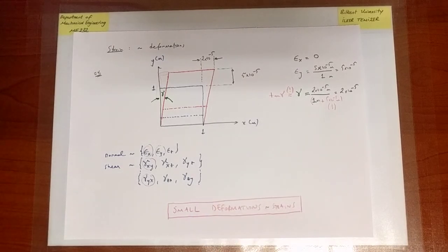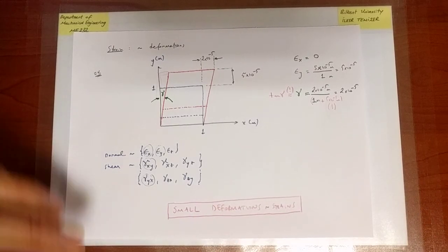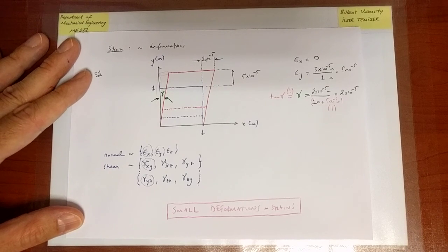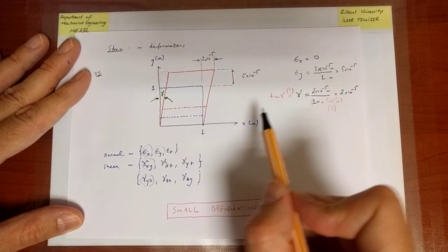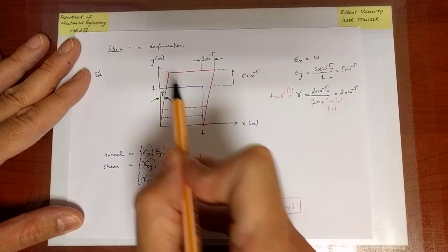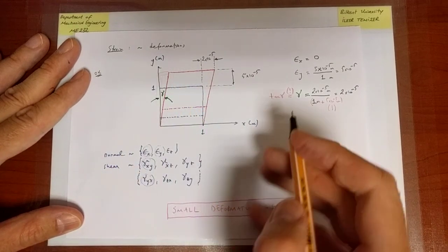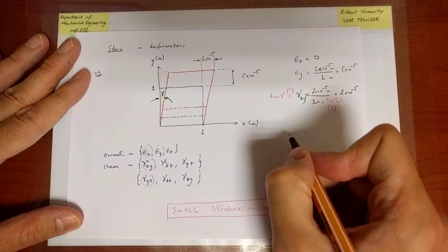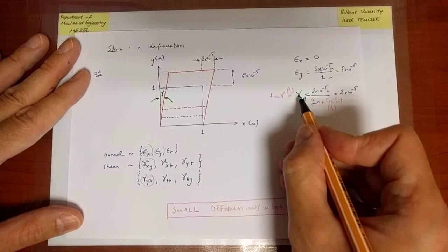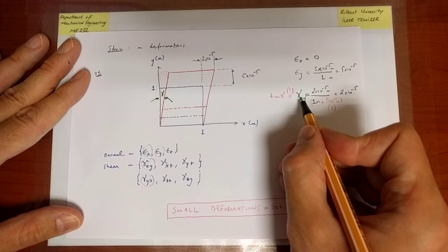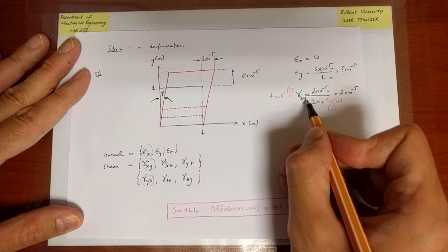Okay, so now that's the shear strain. Which component of the shear strain are we looking at? Well, we're looking at an angle change that is associated with the lines that lie within the xy plane. So this is gamma xy. But it really doesn't matter whether I look at the angle change between lines that lie within the xy plane or in the yx plane.